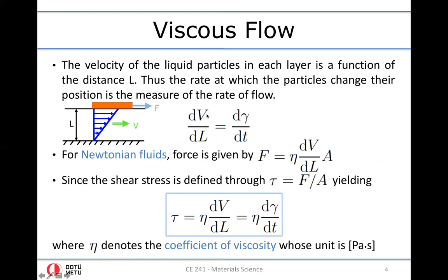Because shear strain itself, remember, is the derivative of the displacement with respect to height, in the two-dimensional setting. So if you change the order of differentiation, you can first take the derivative with respect to time, and then take the derivative with respect to the depth dimension to obtain what we call either velocity gradient or rate of the shear strain.